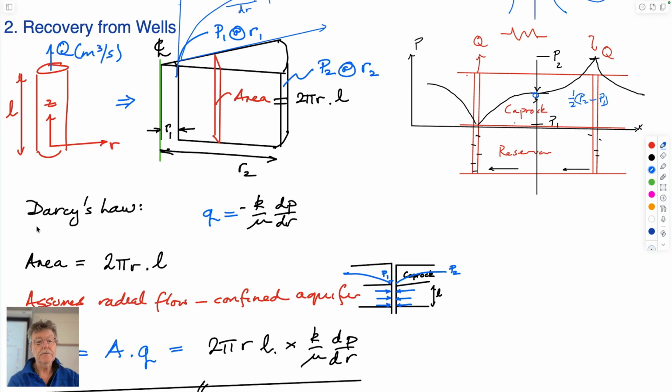And so if we have Darcy's law, we can apply continuity because we realize that if you draw a section across any part of this slice of the cake, the volumetric flow rate across this, Q, has to be the same. Q here is the same as Q here.